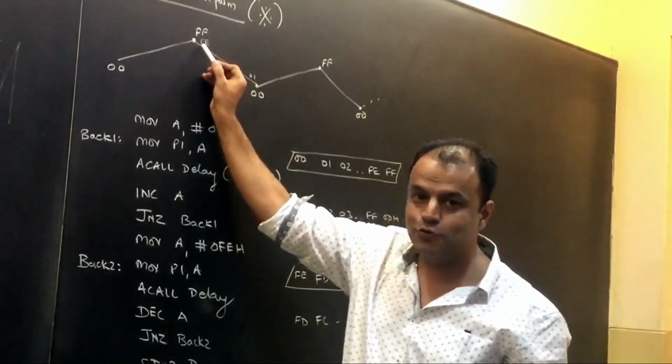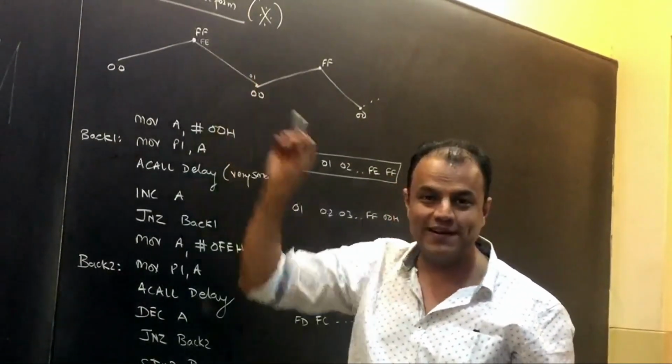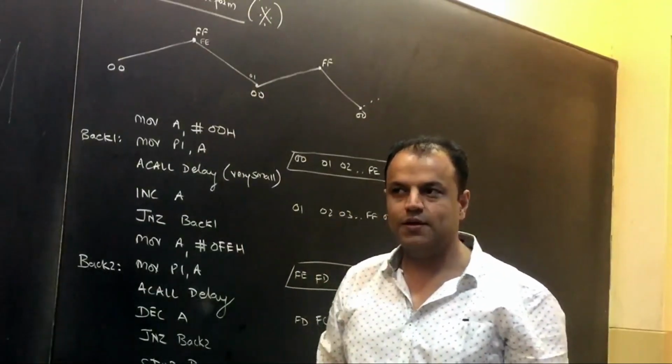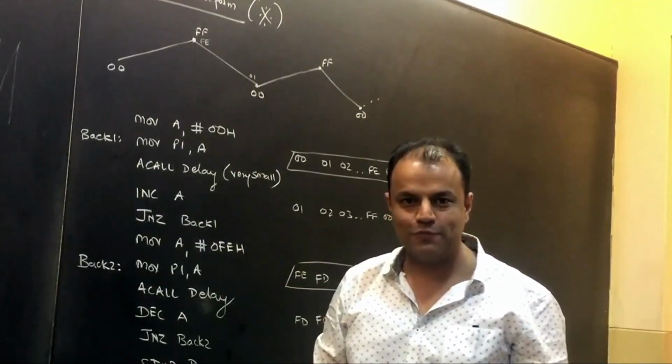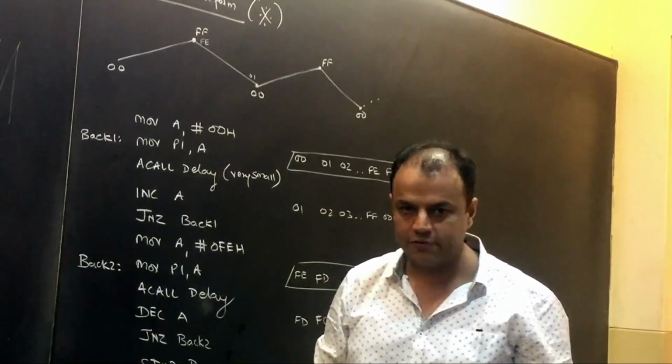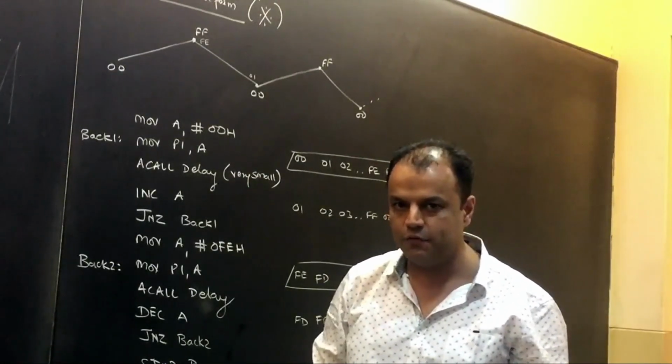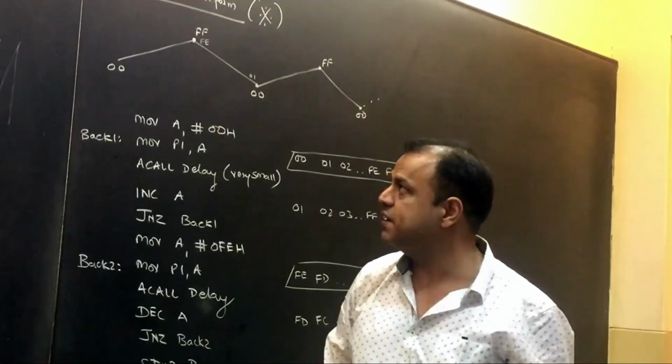If you start this loop with FF, you will have 2 points at FF. So you have a blunt edge at the top. It's not like you will get a 0 for your whole program for doing that, but nobody will give you full marks because it is not technically a triangular waveform. It just looks bad. It's bad programming.